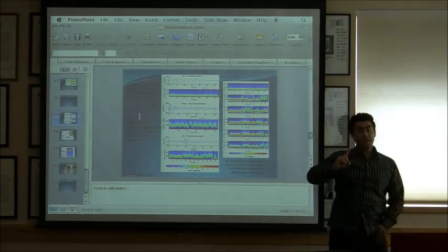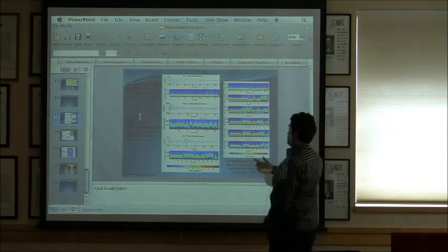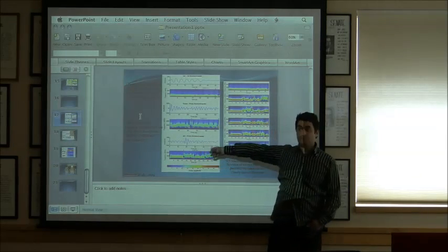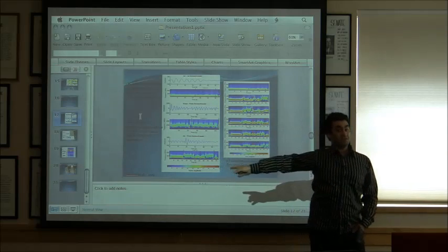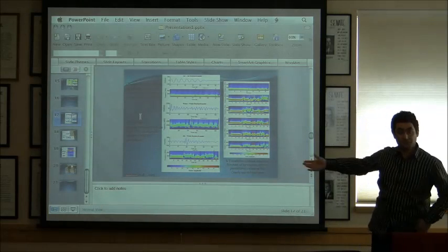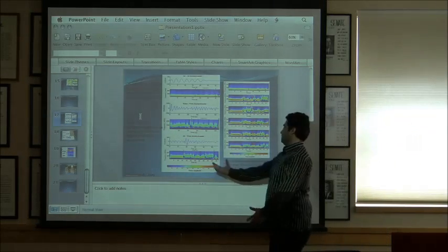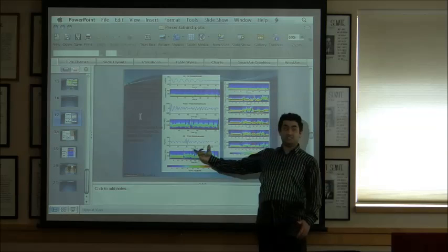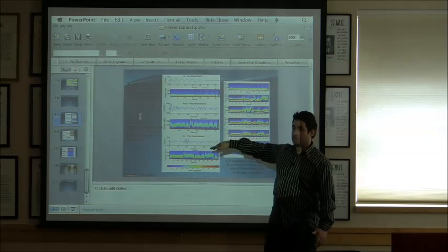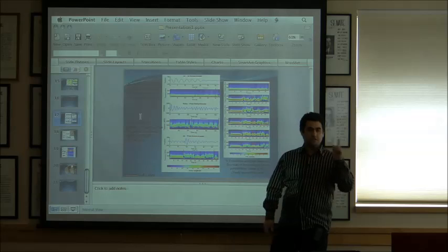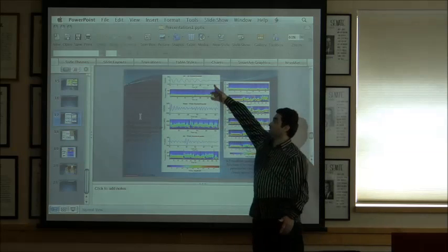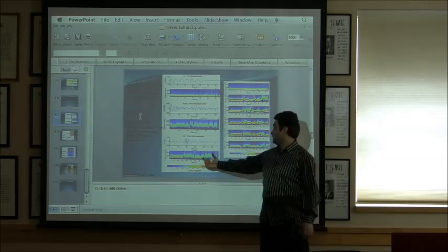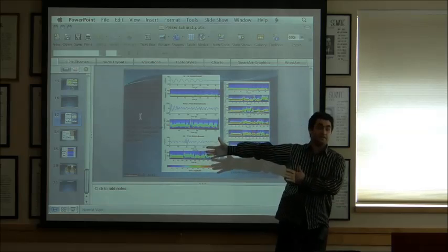When I study GPR, studying fractures, I'm looking for water, for example. I'm looking for that shift. Once I get that shift, I can run the whole thing on all the radargrams I have, with thousands of these, and only reconstruct the water location and ignore everything else.